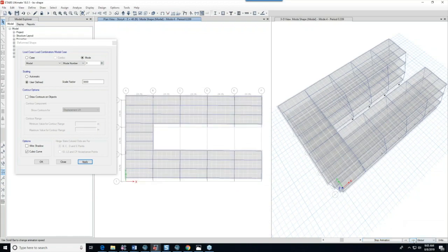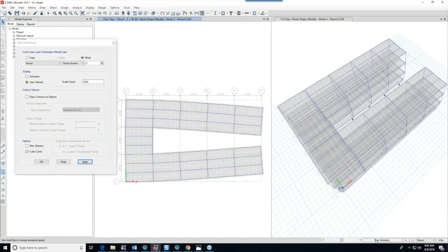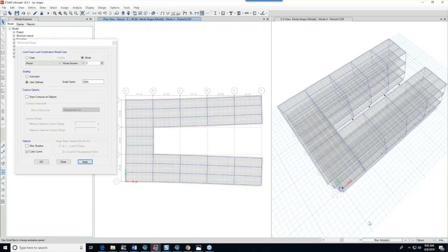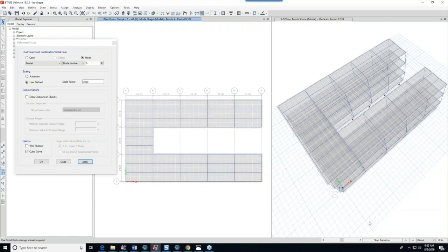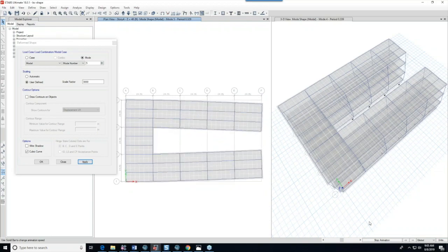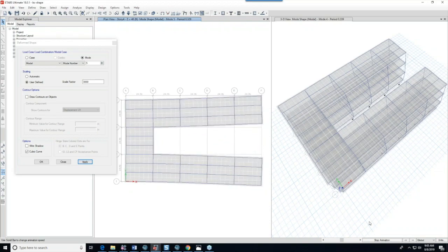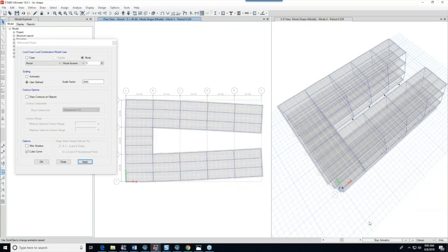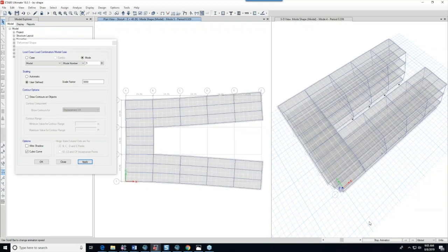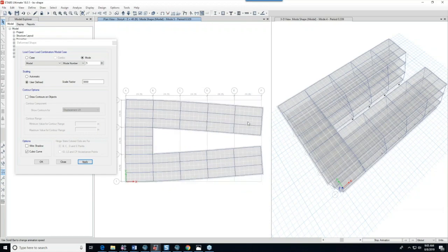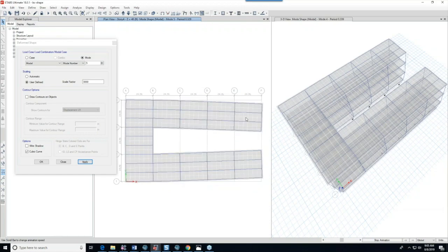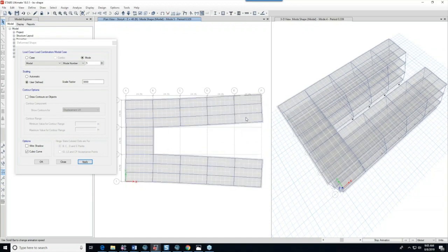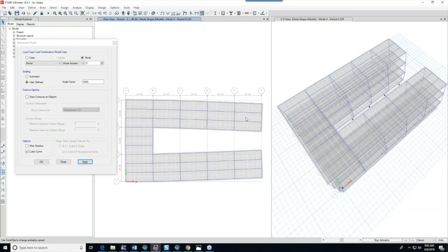But if I look at another mode shape here, then clearly you can see that for this particular mode shape, the floor is behaving as a semi-rigid diaphragm. The difference is the semi-rigid diaphragm approach is going to take into account the membrane stiffness, and it's going to use the material properties and thicknesses of the sections as you've assigned them to your model to account for the stiffness.